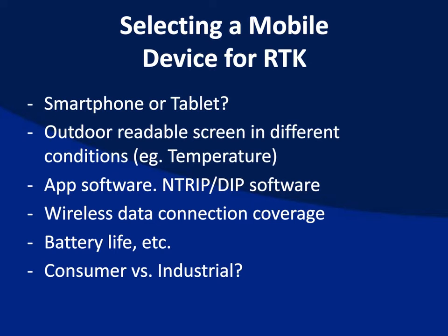There's actually NTRIP utilities for almost all platforms. There's free ones out there for Windows. I'm talking in terms of NTRIP utilities for Windows, Android, some for iOS. You need wireless data connection coverage. You think about battery life. How long do you want your batteries to last out in the field? On consumer devices, sometimes you're only good for 3 or 4 or 5 hours. You need to think about that.